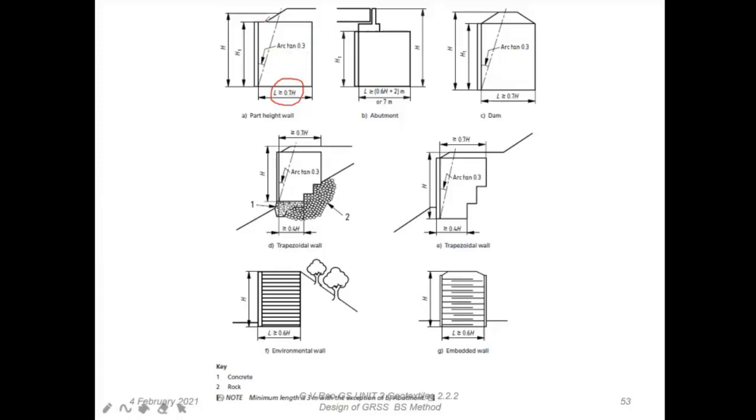So now this entire thing is assumed as a free body. What does free body mean? The whole thing is going to move this way, that way, overturn, horizontally, laterally, anything it can move. So it is a free body now. It is an analysis of the free body which you are going to do, initially without bothering about the presence of the reinforcement within the body. So the whole body can slide, let us say. The whole body can overturn. These are two things now. The whole body is going to give load, the bearing pressure, on the bottom of the foundation. So the three things we are going to do are for the so-called external stability.